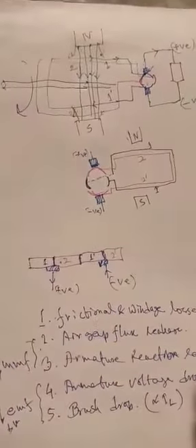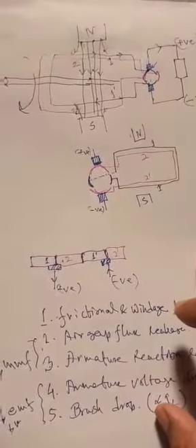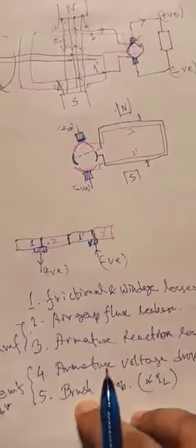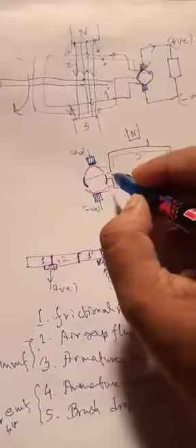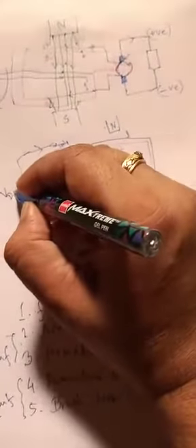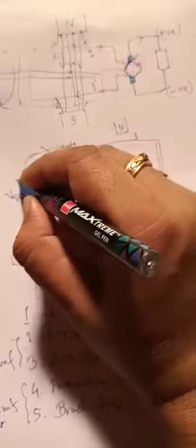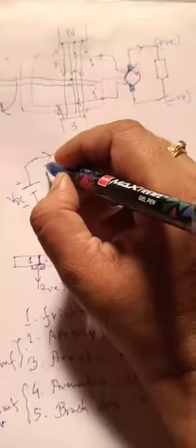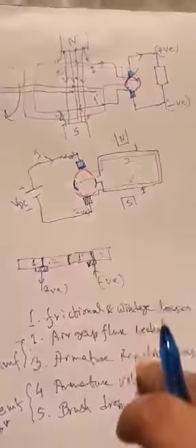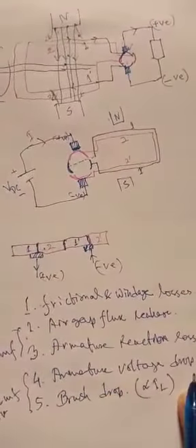In case of a motor, this just happens in the opposite way. If we consider the second one as a motor, then at very first, from any DC source, if we supply VDC, and supply a current I, then it will come through the brushes and the commutator segment setup, and the first loss will happen, that is brush drop loss.